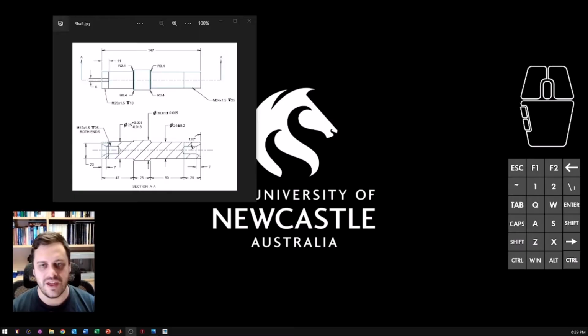The general rule of thumb is if something is cylindrical, such as the shaft on the screen, that's when you typically want to use a revolve. You could model this using extrudes, but from the design intent perspective and to become a more efficient modeler within CAD, you certainly would want to use a revolve in this instance. What gives this away is these little diameter symbols on the screen. That's indicating to me that they're a cylindrical object, and that's generally when I would use a revolve.